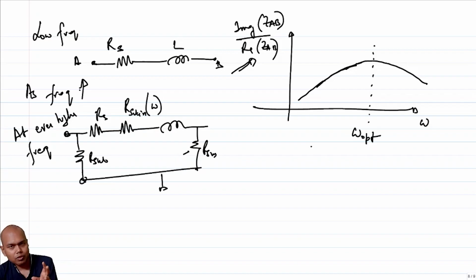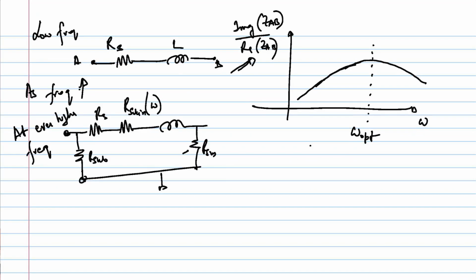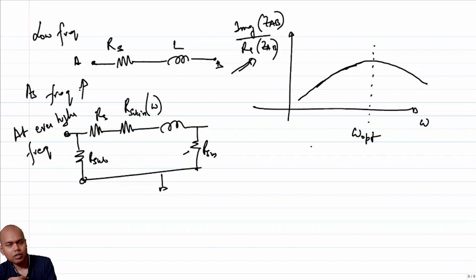So effectively I save area to some extent, and given that having a larger area also causes large parasitic capacitance to ground, by making the area smaller, I can reduce that parasitic capacitance without being affected by the resistance as much, right?